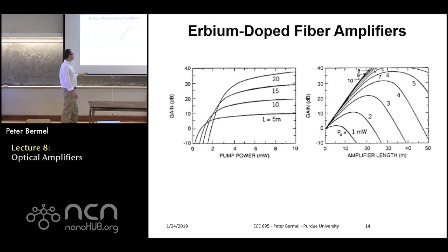And then if you want to see it broken down more discretely, this is showing you, for this 1 milliwatt fiber, that once the amplifier length reaches a certain threshold, you're getting out of population inversion, and the gain actually goes below 0 and starts becoming negative. That means it's becoming a good absorber of your source.